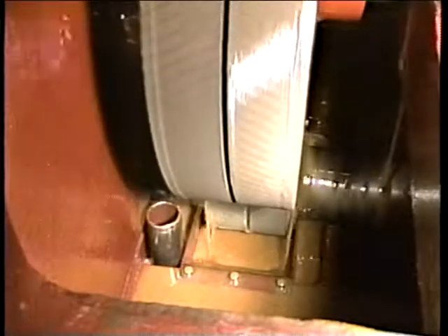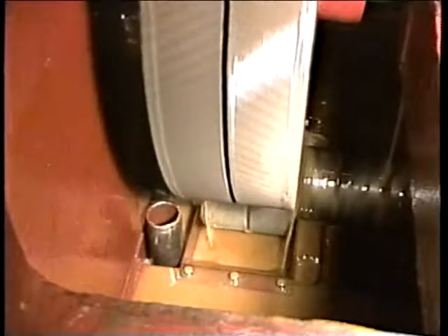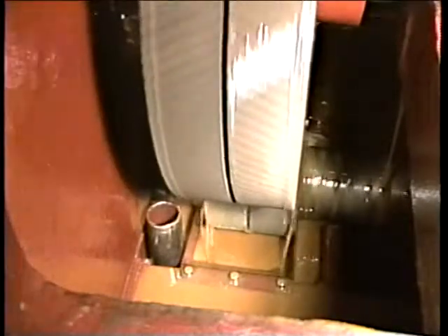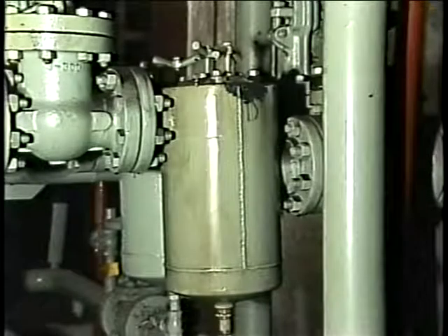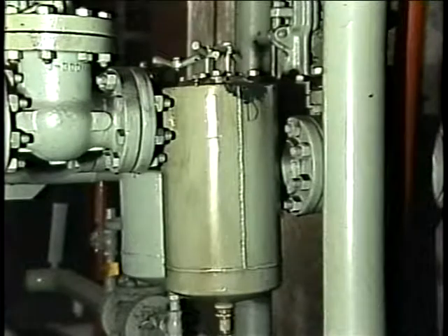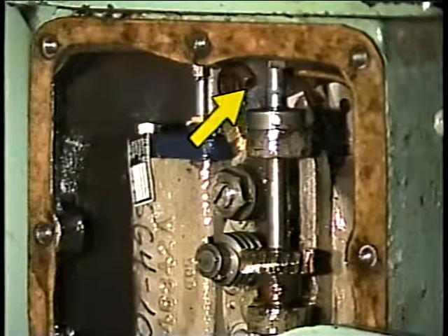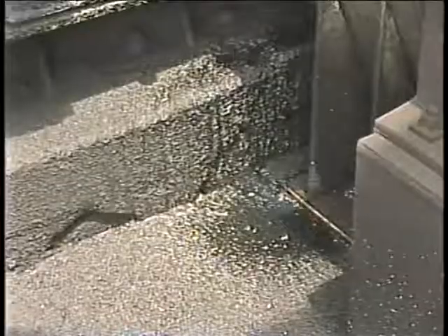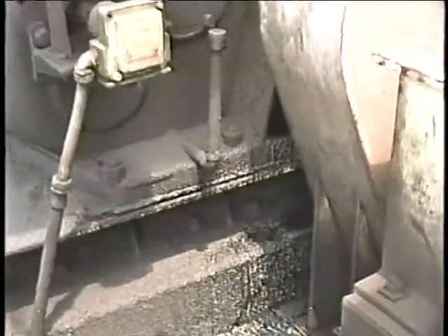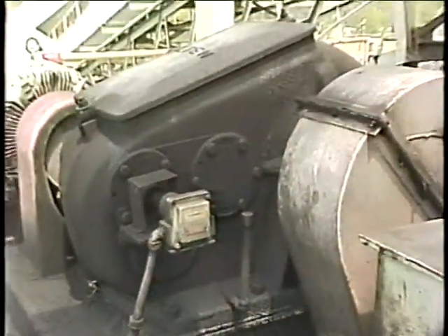If a lubricating system does not lubricate all of a gear's tooth surface before they mesh, overheating and excessive wear may occur. Insufficient lubrication can be a result of clogged filters, clogged or improperly adjusted spray nozzles, or the improper operation of the lubricating system. Also, lubricant can be lost from a gearbox through a blown seal or a leaking joint.